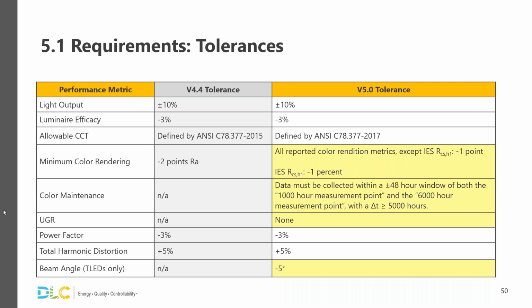Okay, thanks. Let's continue on with the light distribution topic. Is BUG only required for each unique distribution offered? So I'll take that one. Okay. BUG rating is required for all products in terms of reporting on the application form. And only for the parents, for each unique distribution, will it be calculated by the DLC and listed on the QPL as tested data.